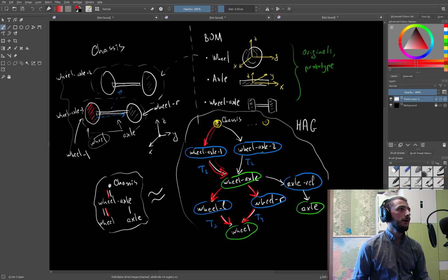So this is how we basically design assemblies, and this is a structure which you would normally have in a STEP file, and then you can read using OpenCascade. You can read it into what is called XDE, which is the Extended Data Exchange Framework.